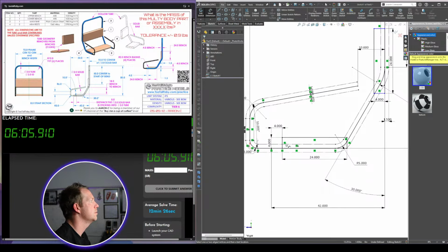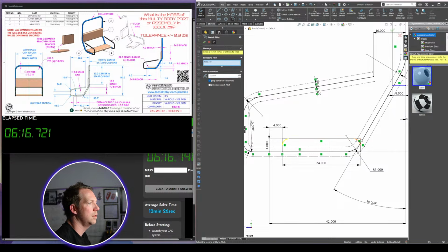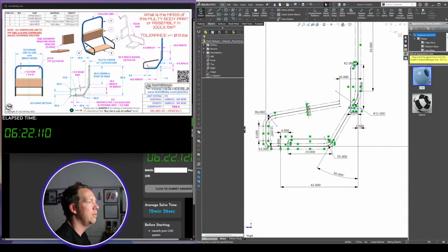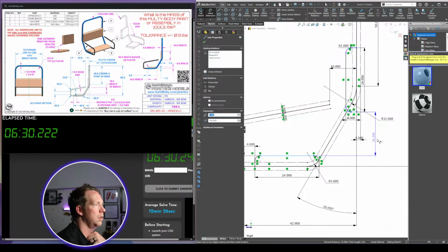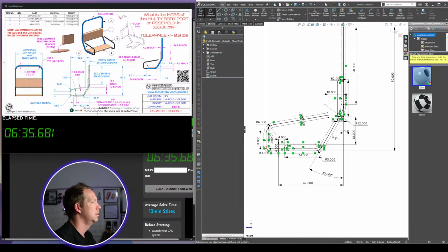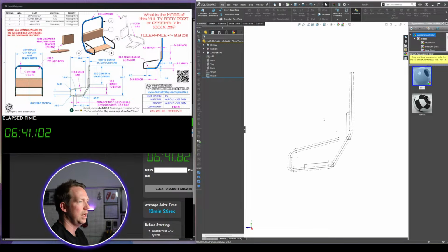Okay. It also has a 2 millimeter radius on the top, which, let's put it in. So there, and there. Okay, that one's fully defined. This one over here is then a gap 18 mil bench to bench. Alright, is there anything else we need in this sketch? I don't think so. Alright, so there's a lot in that sketch. It's probably not easy to just use that sketch.